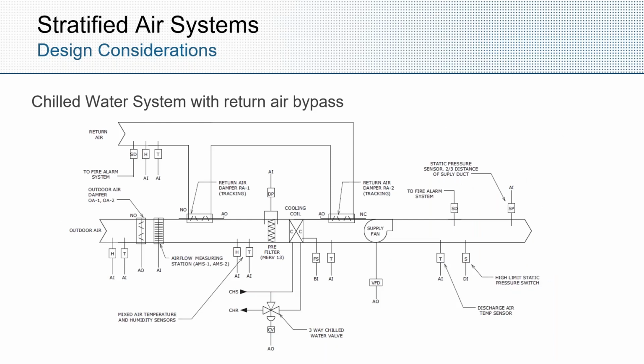And then the last thing I want to talk about is the last change. I mentioned upstream of the diffuser, there's really not much difference as a VAV system. The one thing that is different is the supply air temperature. In terms of dehumidifying, we don't want to change how you dehumidify the air for a particular climate or space. So you still want to cool it down to 55 or cooler if you're looking at that for a particular ratio in the space.